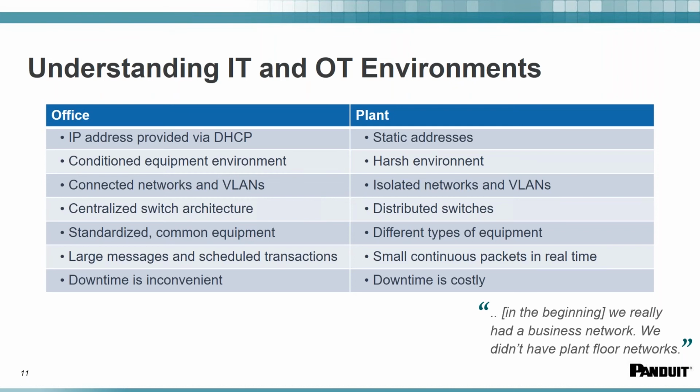When you are designing an automation system, you decide beforehand what is the IP address of each one of the controllers, each one of the switches, each one of the routers, all of the different I/O substructure. You know how it's communicating to what switch, to what network. All of this is determined and fixed. That is not the case on the office side. And that's a major difference between the two networks.